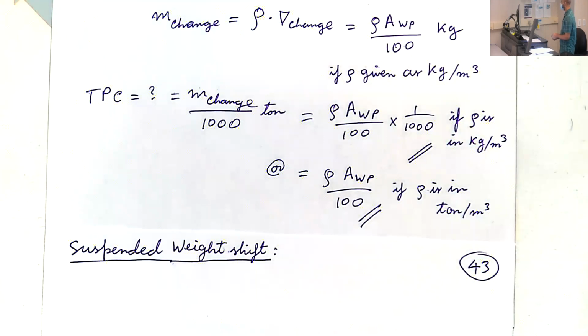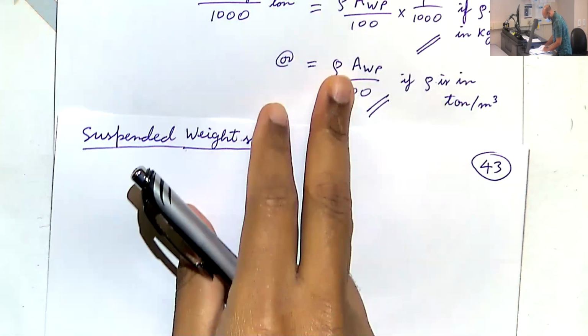And the second thing is, if you have an onboard crane, as soon as it lifts the cargo up from the floor, you have shifted all of your weight from the bottom, the hold of the ship, to the top of the crane. So that's a huge disadvantage. Remember, we don't want the center of gravity to be so high. So if you don't design the ship correctly, it can actually capsize.